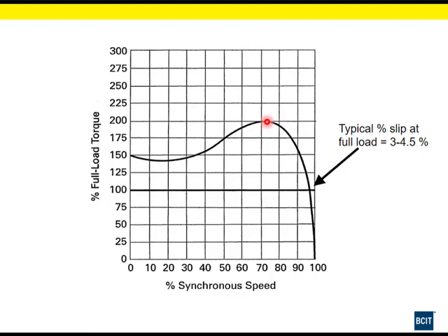And then once we get up to this point here, our power factor gets quite good, and our rotor voltage gets quite low, and then now our actual available torque drops really low here till we get to a full load, or as you notice way down here when we were at 0.5% slip, we're typically using 25% of full load torque.